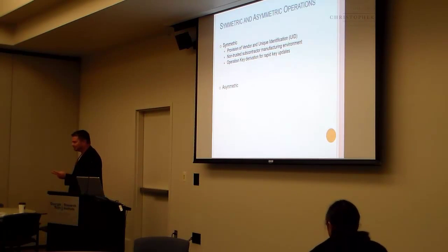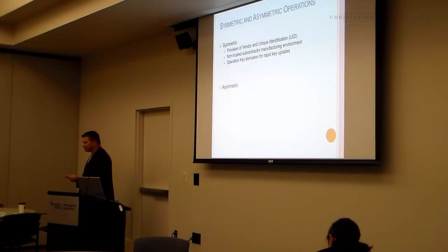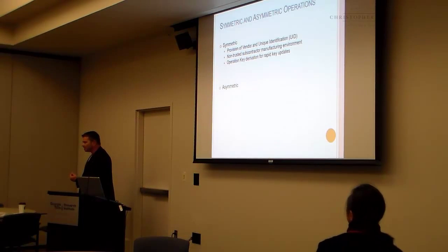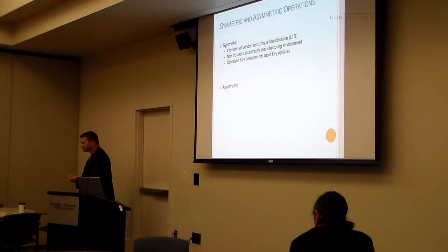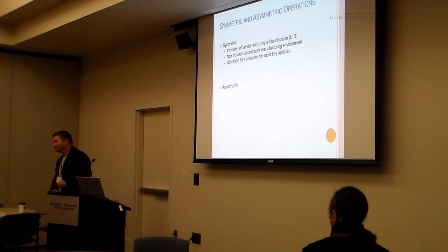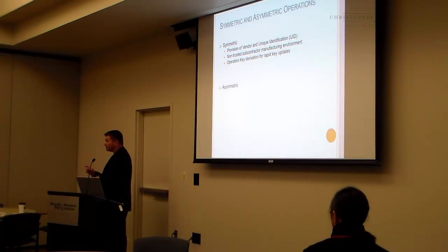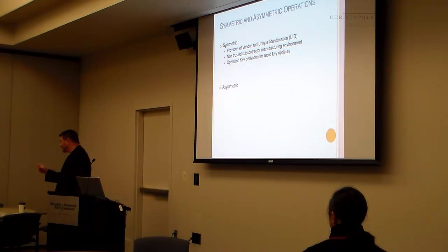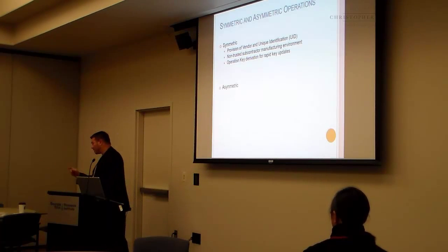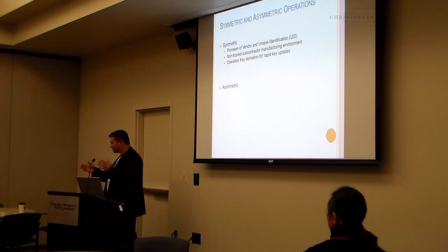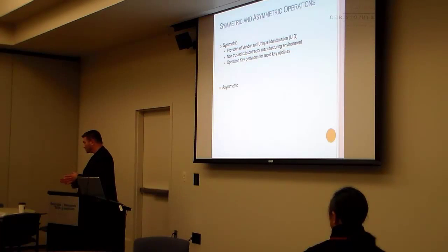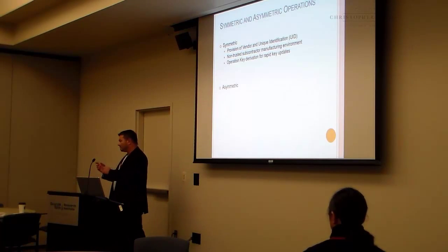But AES is so much more powerful, and this is for another course, because using AES somewhere in the control system might take it down. I think it's too much, but AES has predictable time for operation. It's deterministic, you know how long it's going to take to implement each transaction. DES and AES are kind of the same way. With those symmetric algorithms, you can predict how long it's going to take. So they fit well into deterministic communications for machine operations.